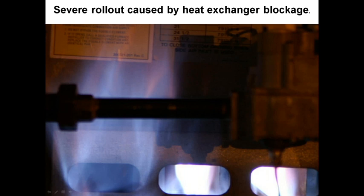All right, this is an interesting one, because you'll run across this periodically, and we talked about the flame starving for air, right, looking for air. This is blockage of the heat exchanger. So this is a bird that got down on top of the heat exchanger cell, and it's blocking the cell off when the furnace starts up. If the flue gases can't exit, it's going to come out the front looking for air, and that's exactly what happened here.